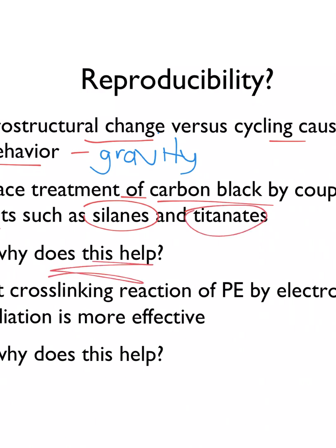Why would this help in this context? Sorry, I thought you were asking a question. I'll just keep going. So why would the presence of coupling agents help resist this process? Well, for one thing, if there's coupling agents, they might form sort of a dense mesh, I want to say, and kind of prevent the carbon from slowly sinking through to settle. Yeah, basically. So we talked about coupling agents, especially silane coupling agents, as a way of providing a direct polymer to solid particle chemical bond.